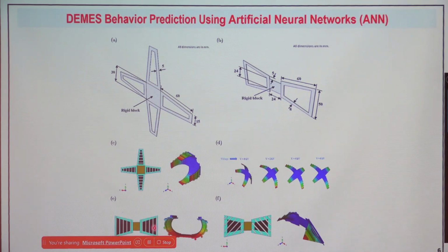So this is input. One of the inputs is also voltage. You have to give the input voltage. When you are defining the actuated configuration, you have to define the voltage. So this is also your input. What is the output? The attained initial equilibrium angle, or initial angle. Final angle when voltage is applied. And this gap, initial minus final, is called the actuation stroke or actuation range. Clear? This data, okay.